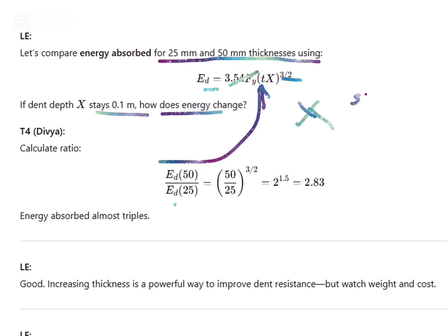You can calculate the ratio. You can see that it's almost triples. If we double the thickness, energy absorbed almost triples.